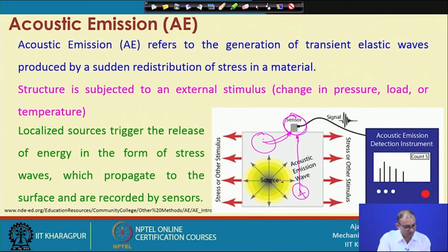And if you do machining, we know the maximum deformation takes place at the tool and workpiece interface, but we also know that it is difficult to put something there. So, we have to put any sensor, let it be an acoustic emission sensor or the dynamometer, as close to the machining condition as possible to get a reliable signal.